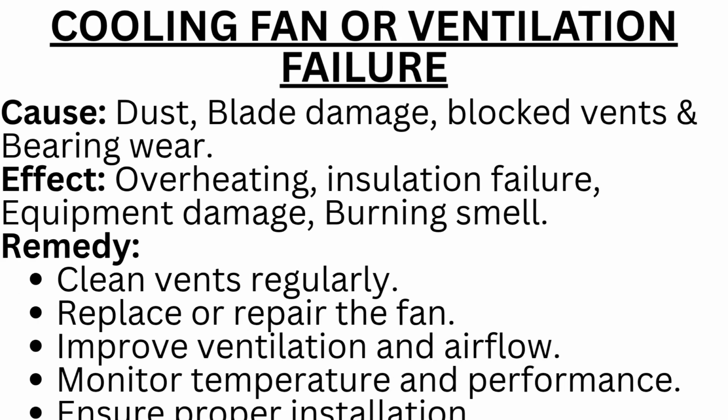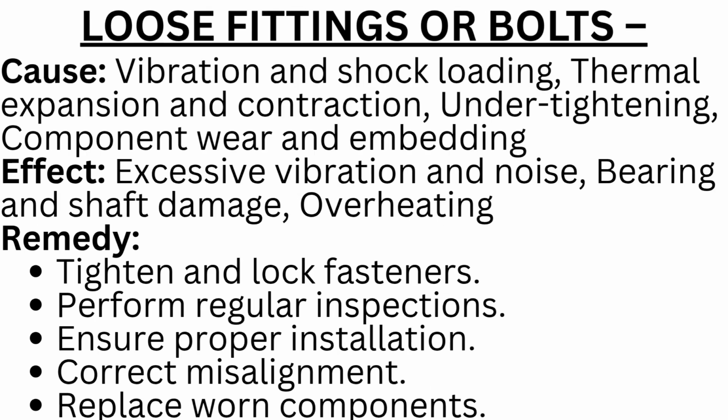The next mechanical failure that we will look at is cooling fan or ventilation failure. Cause: dust, blade damage, blocked vents and bearing wear. Effect: overheating, insulation failure, equipment damage, burning smell. Remedy: clean vents regularly. Replace or repair the fan. Improve ventilation and airflow. Monitor temperature and performance. Ensure proper installation.